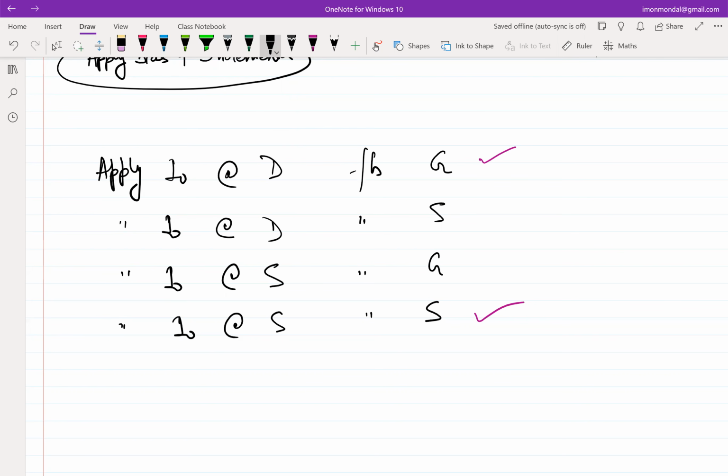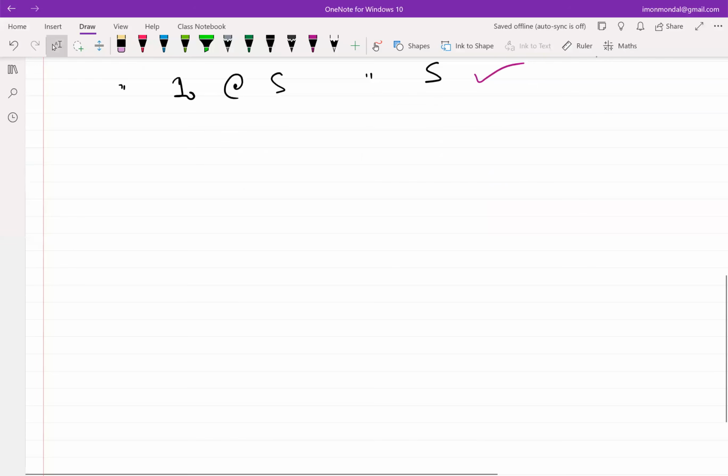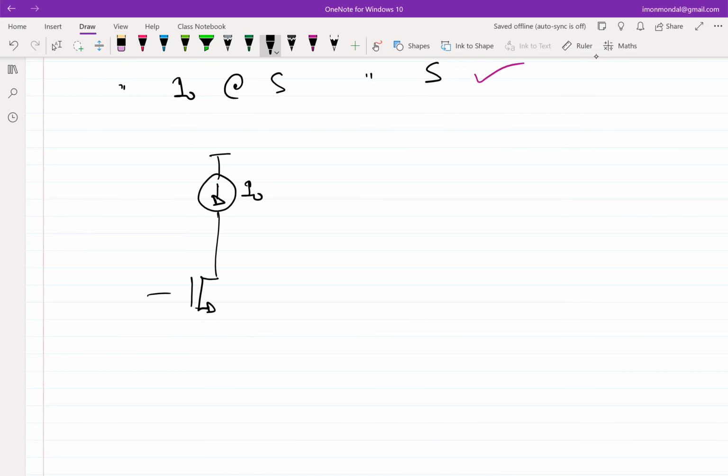Okay, so let me take this into account. We will apply the current source at the drain, and we'll sense whatever is happening at the drain voltage and try to tweak the source terminal. Obviously you need to have a current source, and we already said that we'll be tweaking the source, which means that my gate has to be some constant bias. So we'll have to apply something at the source, right?